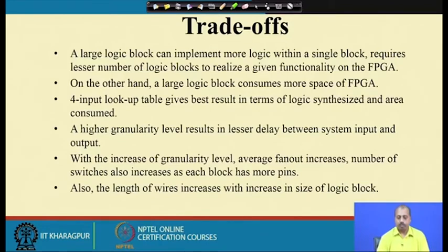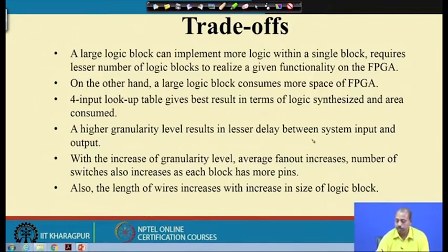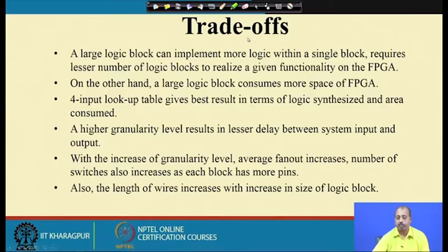If you look into this FPGA chip, as we have shown, if these are the logic blocks and say this is another row of logic blocks, we have got interconnects running between them. If these logic block sizes are large, then naturally this interconnect length is also going to be large. That is another problem. If you have got larger sized logic block, then the length of the wires will also increase. So, it may be better that we go for smaller size logic blocks or finer logic blocks.